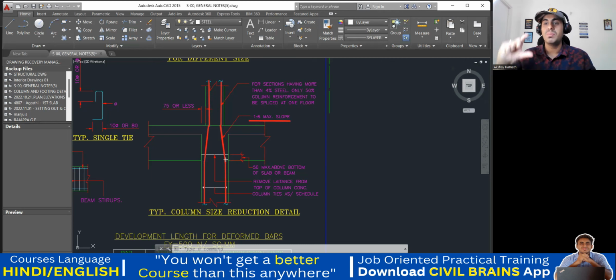So a small gentle slope, like when you do lapping, this is how you bring a bar. A small bend you'll give, and then take the bar like this. For lapping, the same thing you're supposed to do here. Only this particular portion you can extend a little, something like this. Got it? This is what it is trying to tell us.